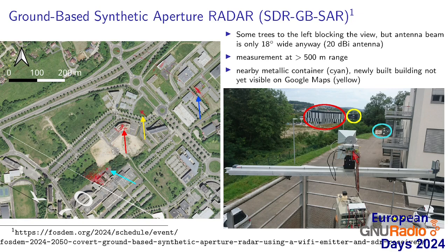Now, in a synthetic aperture radar, range is provided by the bandwidth of the signal being broadcast by the radar, but azimuth, meaning the direction of arrival, is provided by the spatial diversity of moving the antenna here along this rail. In this example, we wish to move the whole setup, including transmitter, receiver, SDR platform, and Raspberry Pi, along with the antennas, but only collect data as they are fixed in a location where the antenna position is stable.